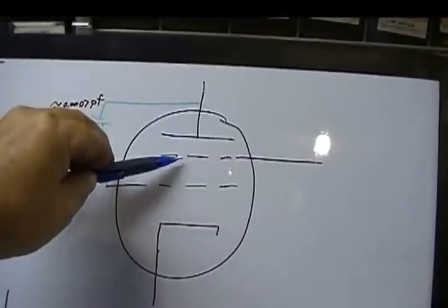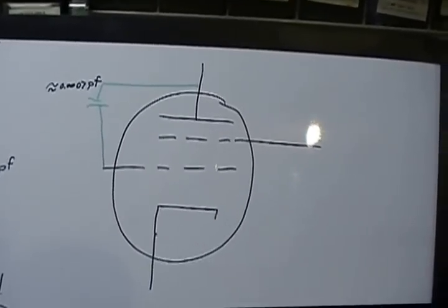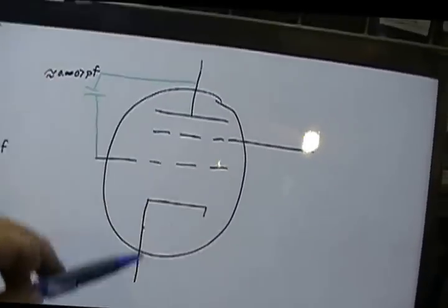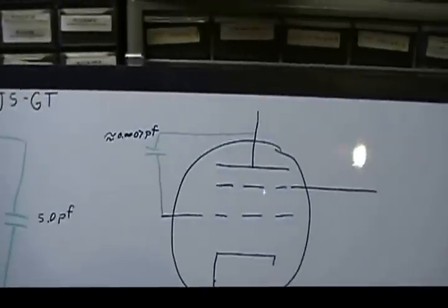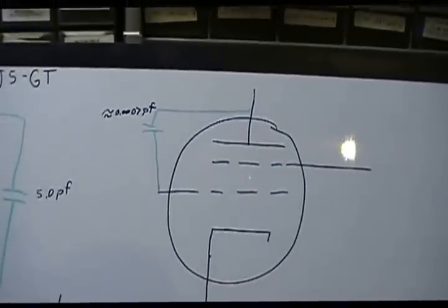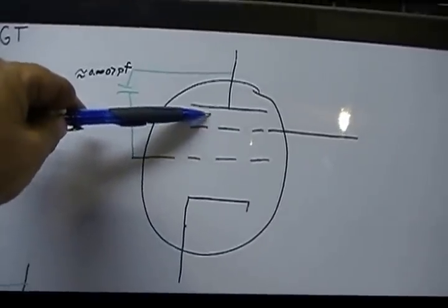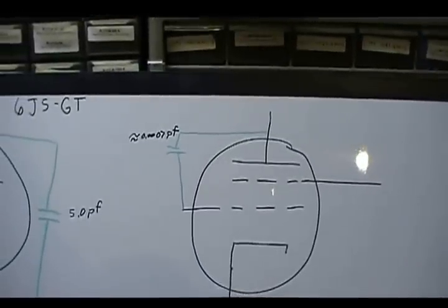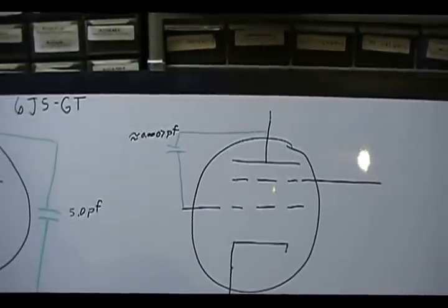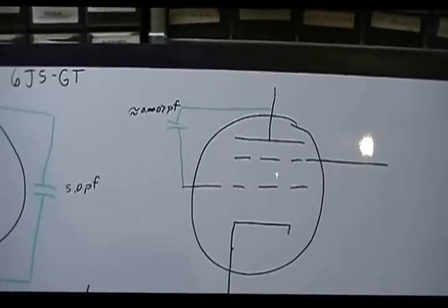The plate is a higher voltage, so it draws them even more. Between the two, we've already increased their speed tremendously as opposed to a triode. What that tends to do is, when you get high velocity electrons hitting a plate, if they're moving fast enough, they will actually knock electrons loose from the plate and bounce them right off of there.